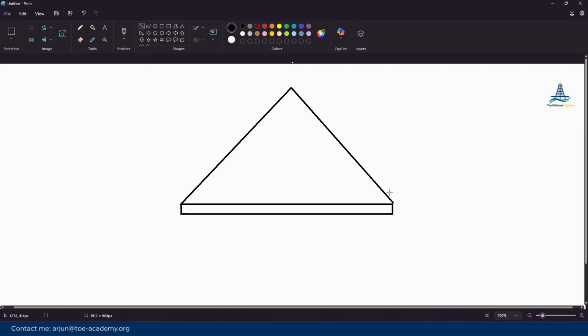Most of the time there will be a pad eye, so we need to account for the pad eye as well. What I always suggest is you need to model that pad eye part again. From this center point, you need to have a dummy member to account for the pad eye. Then from this pad eye, you can connect the slings to the hook point. So first we are going to model this dummy member for the pad eye. Then we need to have the hook point.